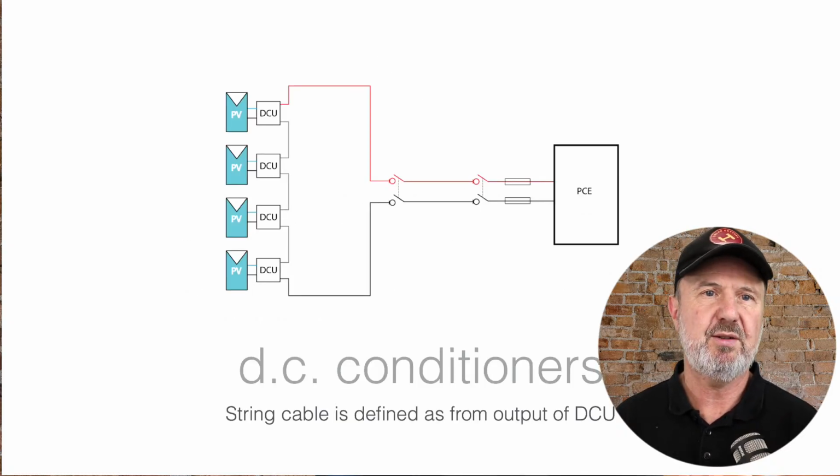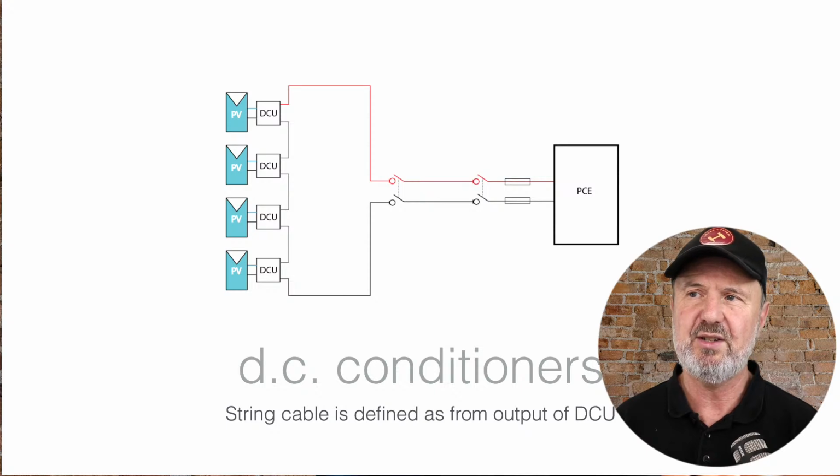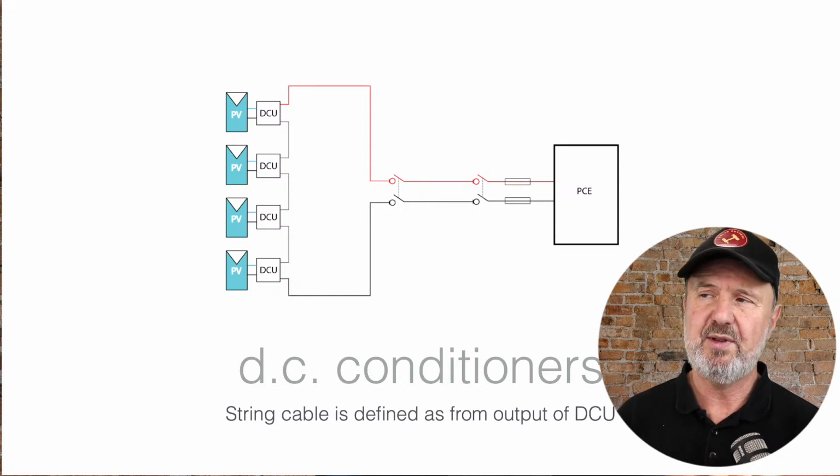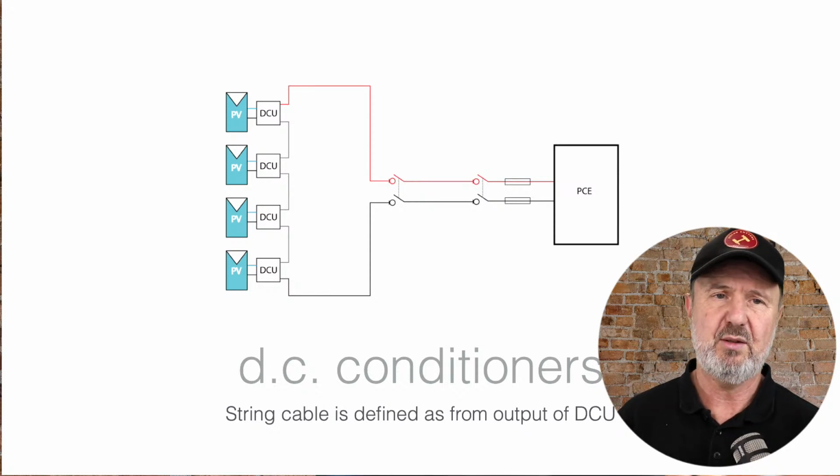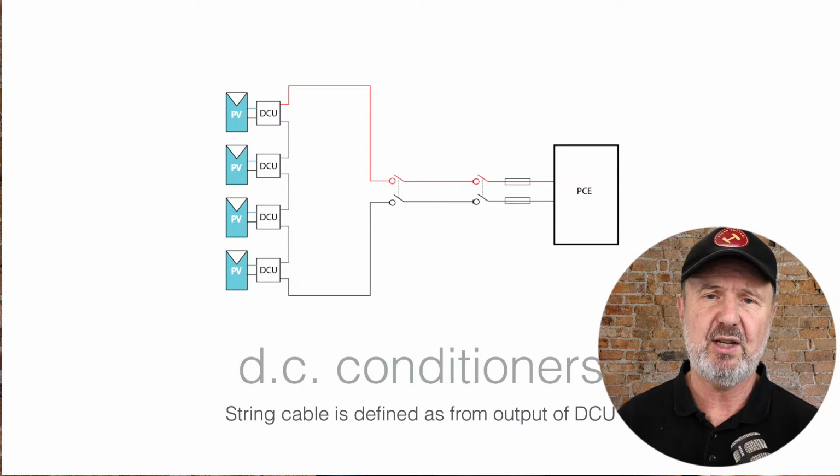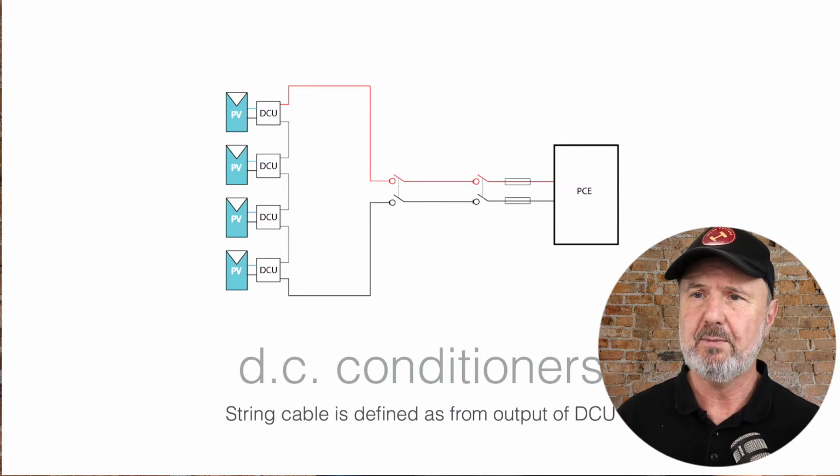And there's a picture of the DCUs and explaining how they work. So each one interfaces between the PV array and the string of panels that are connected together in series, and therefore they are controlling the string voltage collectively. In fact, there are different systems for this. Sometimes the inverter, in this case, we use the generic term PCE, power conditioning equipment, because it may be other than an inverter, but generally it is. It's telling each of those DCUs what their current and voltage should be to get the target string voltage that the inverter wants. So that's how they work.